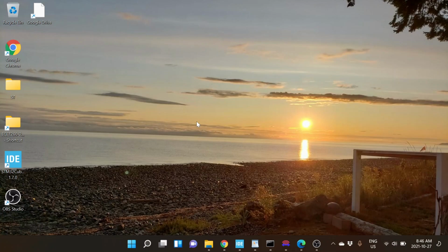That's typically what you'll see by default when we've hooked things up, okay? But you can change that. And if you had 1 stop bit, we will go to a stop bit, and then it will just roll into the mark level, okay?